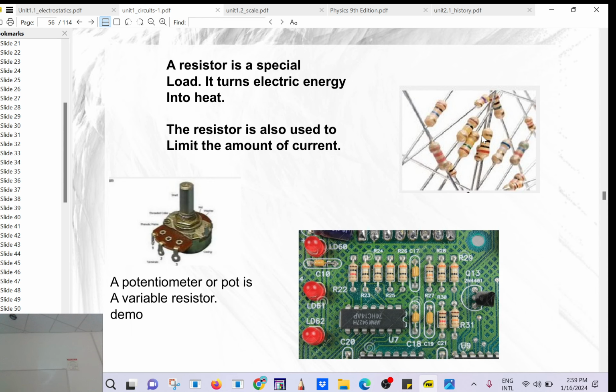To measure the resistance, you take the resistors out of the circuit and then you measure like this. For example, this one, if it doesn't move, what do you read? 15 ohms. Do you see that?